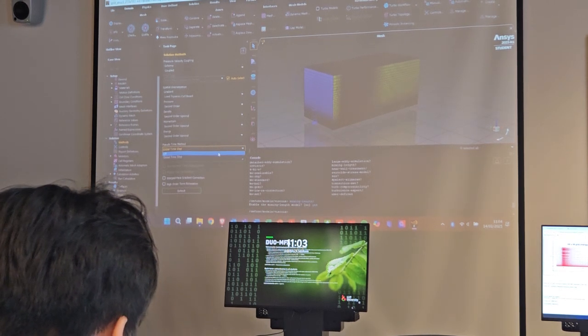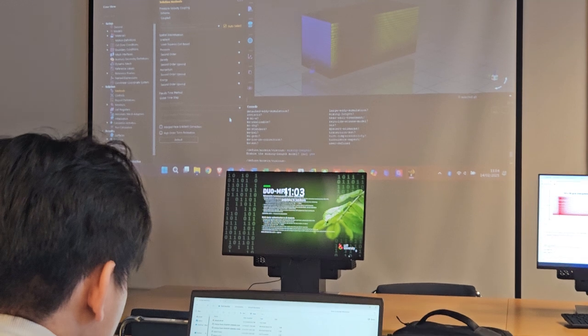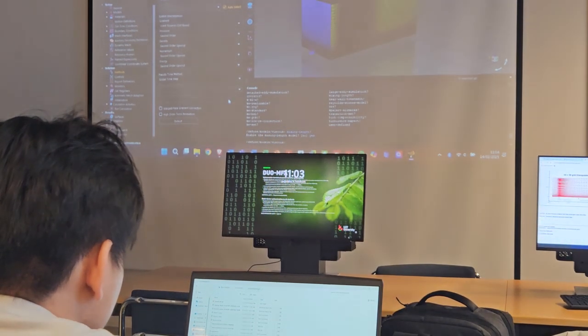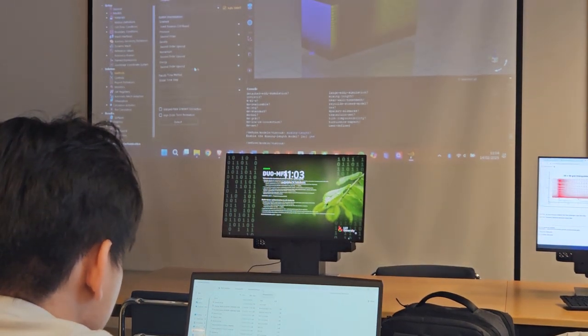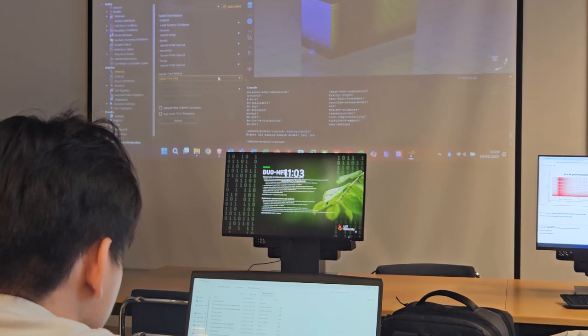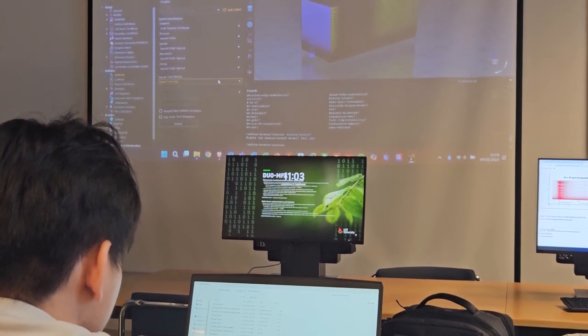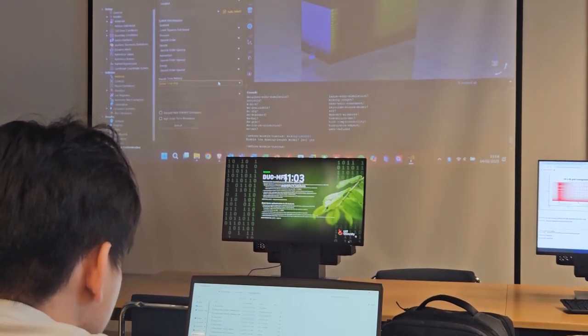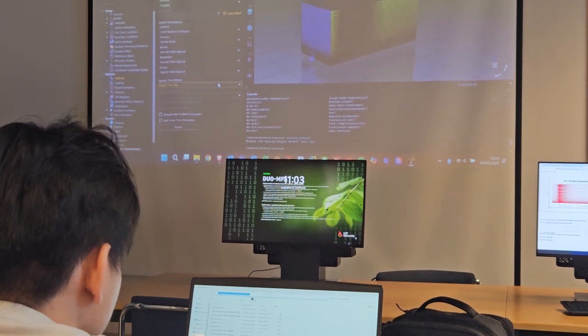Otherwise, you can also set it to off, and then you have a different formulation for how you get to the steady solution. Typically, this is quite convenient for most cases. It doesn't require many iterations, it's quite fast, and so we'll go for that.